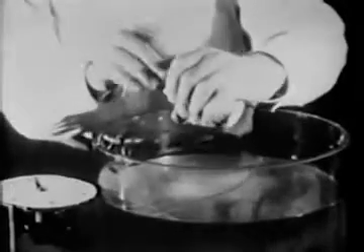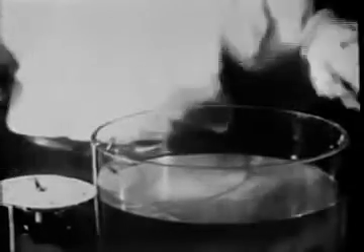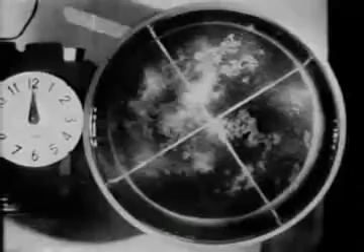Here again is the tank on the turntable, with no motion and with no circulation. Now the turntable has started, but the fluid in the middle doesn't move because none of the agencies which create circulation have yet come into play there. Next to the wall, however, the fluid does circulate because of viscous stresses.